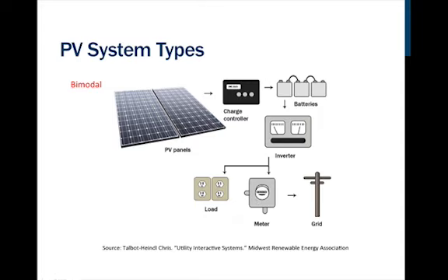If the grid goes down, the inverter physically disconnects from the utility grid, and we're up and running off the battery pack. And this happens instantaneously. We have no physical connection to the utility grid. We're running off the battery pack. The PV array out in the backyard is still producing electricity, tapping off our batteries, and from the batteries to the inverter to our loads.